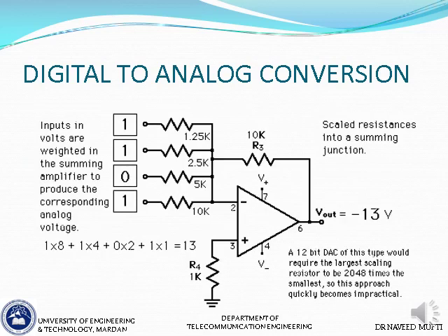So here is our 4-bit digital to analog converter. Because it is 4 bits, it has got 4 inputs here. This is your inverting summing amplifier. As you can see, the input is on the inverting terminal here, and the positive terminal is connected to ground, no input here, so it becomes an inverting amplifier.